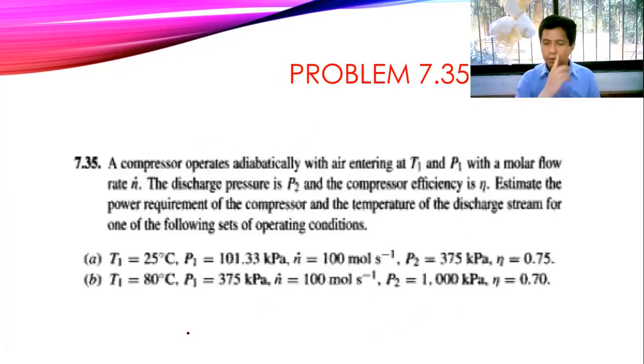Okay, so let's try to solve problem 7.35. A compressor operates adiabatically with air entering at T1 and P1. So T1 is 25 degrees Celsius. Ito yung initial temperature natin. Ito yung initial pressure natin. With the molar flow of N dot, so 100 mole per second.